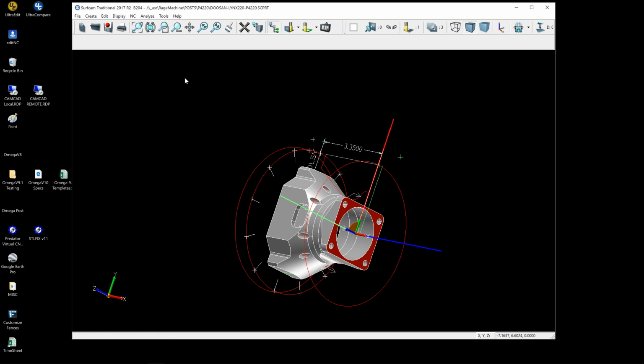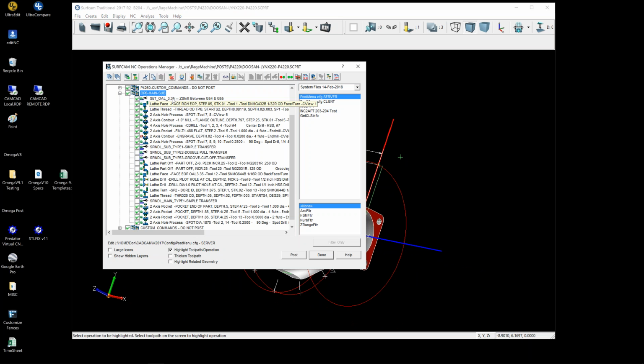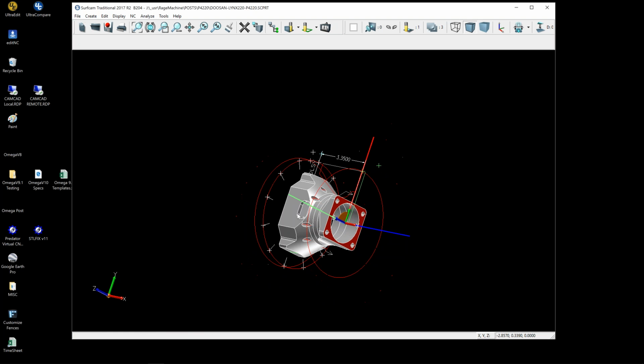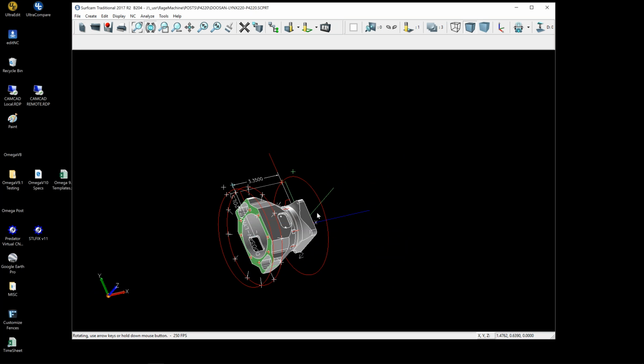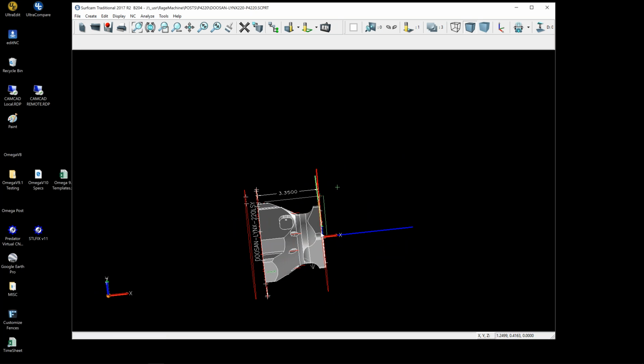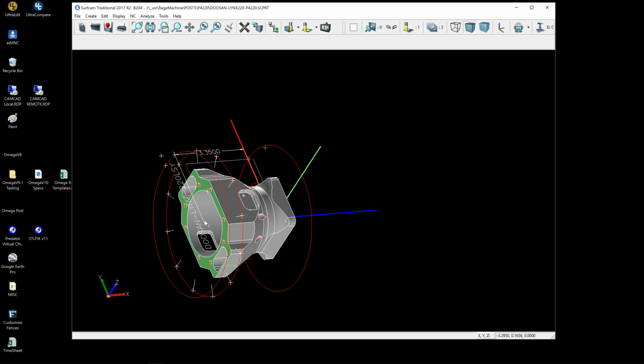And what we do for this, if we're doing main and sub work, we can put in an inline command that has the overall length that sets that. So what happens when we're programming in the sub-spindle, the system adds 3.35 inches to the 0, which is still here coming from SurfCam, so that this becomes the 0 point, coincident or congruent with the work offset, typically G55 on the sub-spindle.